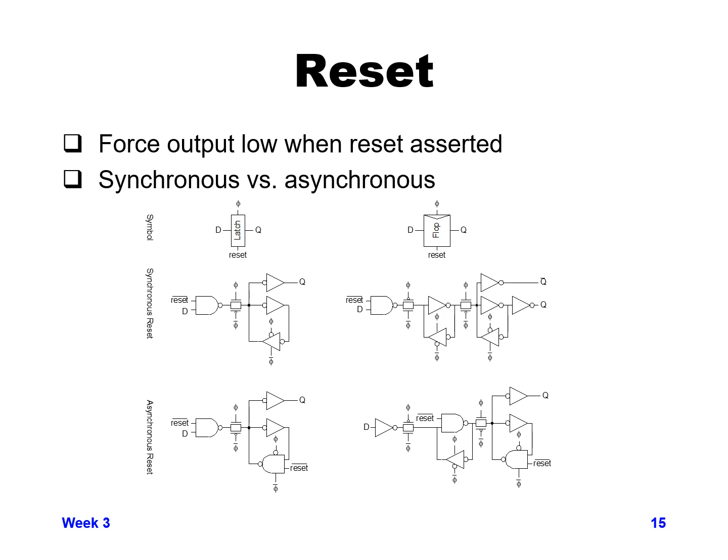So there's synchronous reset, and what that means is, if a reset comes along, we don't just automatically overwrite the value of the latch or flop to the reset value. We still wait for the next clock to come along and sample that result.